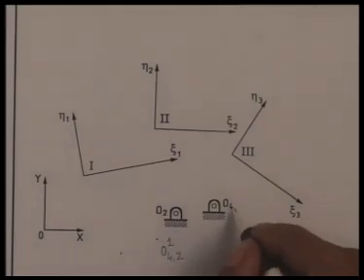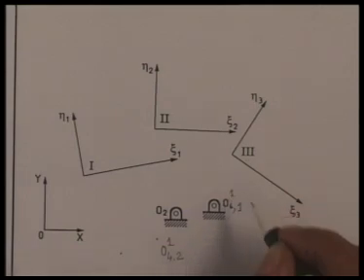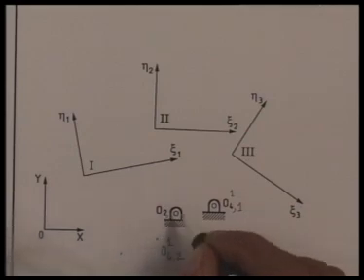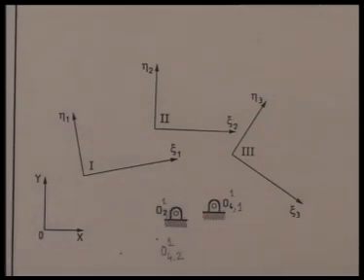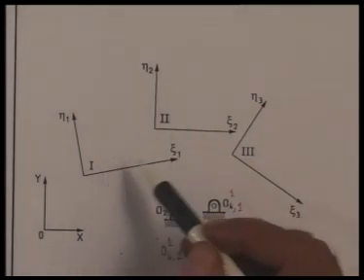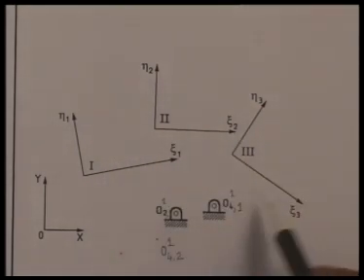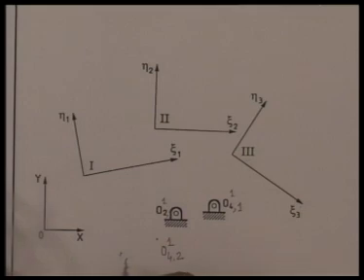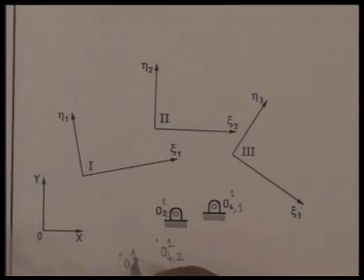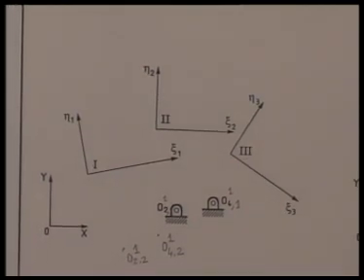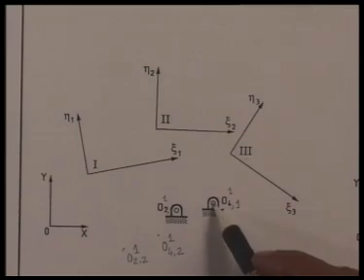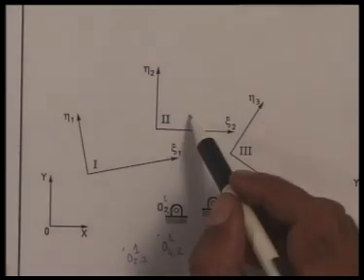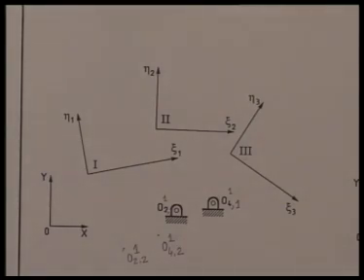This is really, I could have said, O4,1,1. And this is O2,1,1. So holding the coupler fixed in the first position, if I allow the fixed link to move, then O4 comes here and O2 comes here. This I call O2,2,1. I hope it is clear how I get the inverted position of these two fixed pivots if I hold the coupler fixed in the first position.